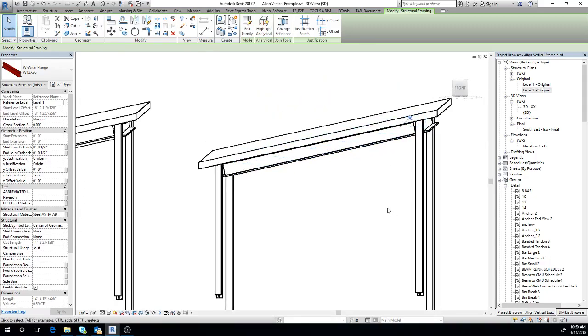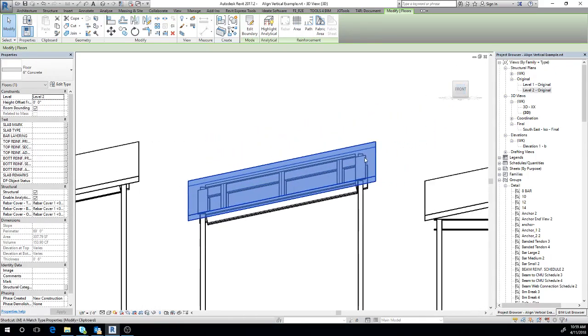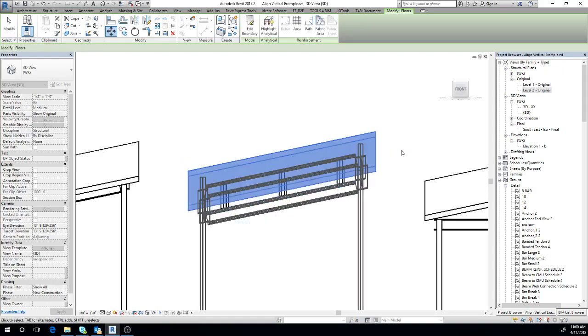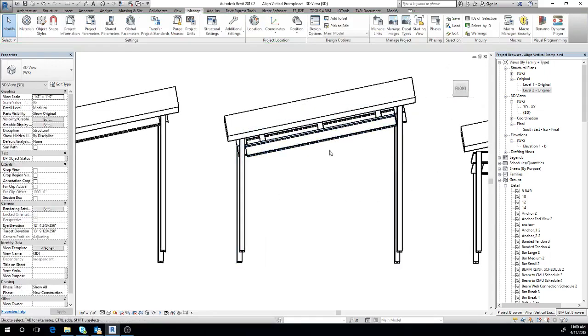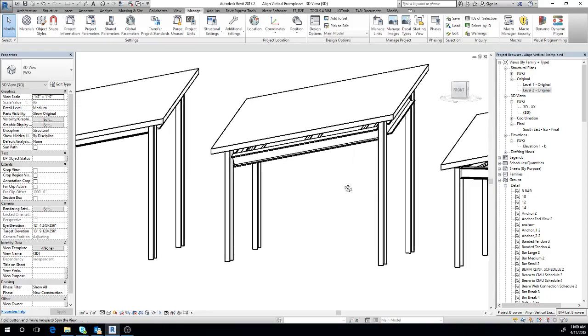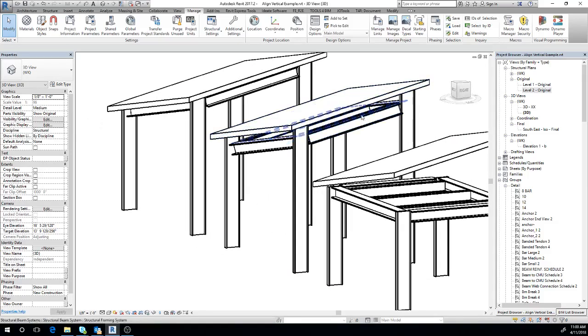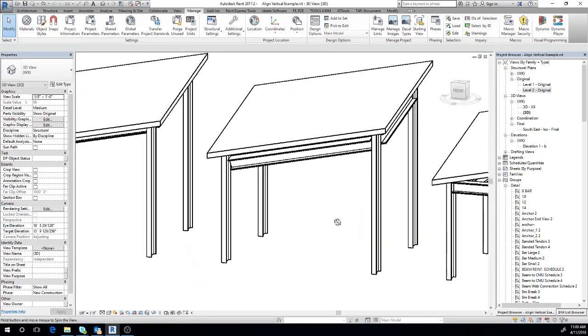Unfortunately, if this top surface were to move, say, up 1 foot, these will stay, but we don't have a way of easily selecting the reference plane that is following this slope, because there is no view that it can be clicked on.